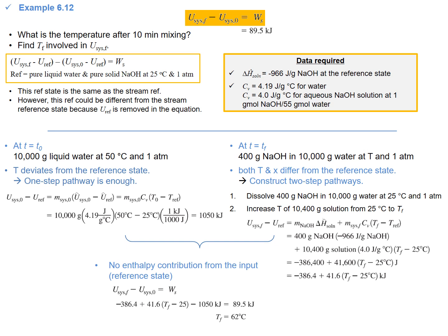Fortunately, even if we have insulated the system, the temperature goes up to 62 Celsius degree, which is less than 70 Celsius degree. That is the safety guideline. So we are safe enough. So we don't need to insulate the tank for the mixture of sodium hydroxide with water.